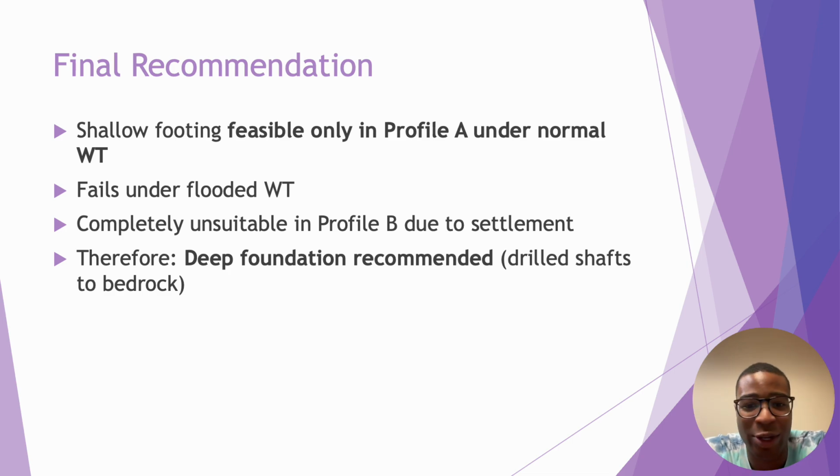It's just that in this case we didn't drill down to bedrock, so we can really examine the soil profiles to see how a sand versus clay decides what you're going to need in terms of support. And drilling down is much more efficient. You're not going to need nearly as much steel, and it's much more economical. And to fit 130 piles into a 20 by 25 foot area is just really infeasible and extremely costly.